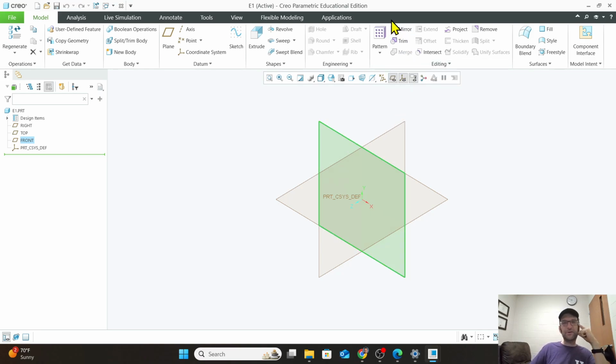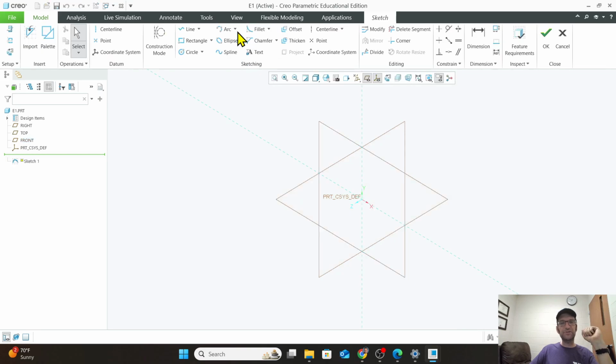We have choices in Creo when we want to start a part file, or we know we're going to start an extrusion, or a revolve type of part, where we revolve a sketch around something. We can go right into those tools and skip the step of choosing that sketch, but we're going to choose sketch just so the process makes a little more sense.